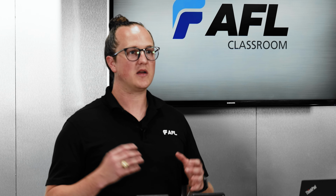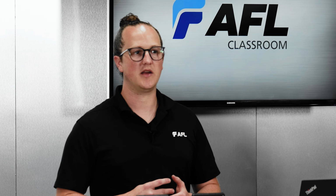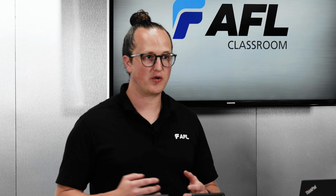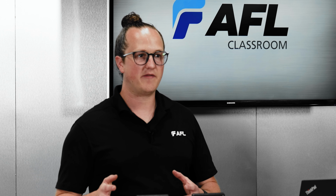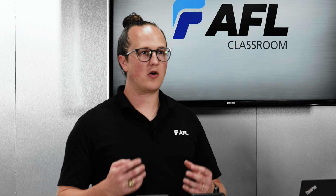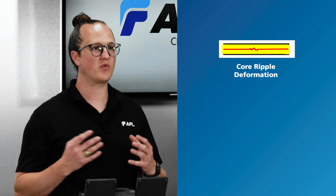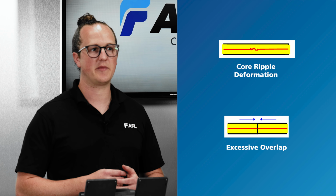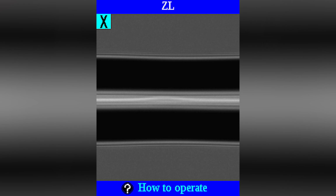For example, maybe the electrodes are worn, causing an erratic arc discharge, or maybe a setting is not tuned properly, leading to poor splice performance. Like the fiber-related conditions, the splice mode parameters can produce some unique image features as well. These are mostly tied to the heating phase of the splice, however, meaning that the arc and the overlap are really the main factors in play. For example, if you see the rippling effect in the core, it's an indication of excessive overlap or insufficient prefuse time and power. Similarly, if you see the core losing definition at the splice point, it's an indication of too much arc power or too much arc time.